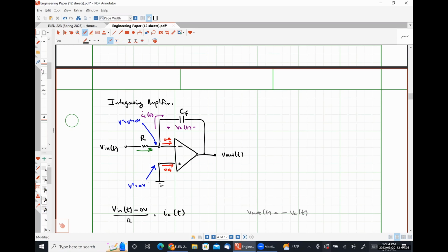Everybody, because it's real loud. That's a 60 hertz hum. If you wanted to not pick that up, you would need to use a filter, probably a high-pass filter that cuts off everything below about 60 hertz so that it doesn't show up on the signal that you're trying to amplify, which is, I believe, this one right here, but I might have gotten it backwards because I'm used to using passive filters.